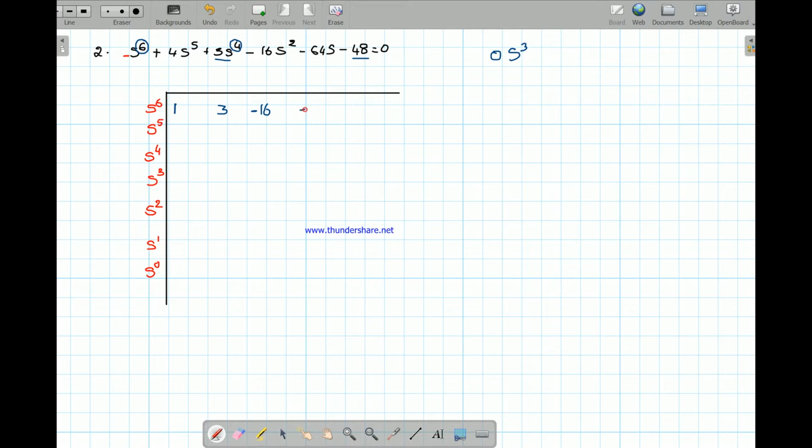Polarity should also be considered, not just the value. If it is plus 48, then it would be plus 48. Now it is minus 48, so we will take the negative value here. So this is s power 6, s power 4, s square, s power 0. Now coming to s power 5, the next row which we are going to construct here.